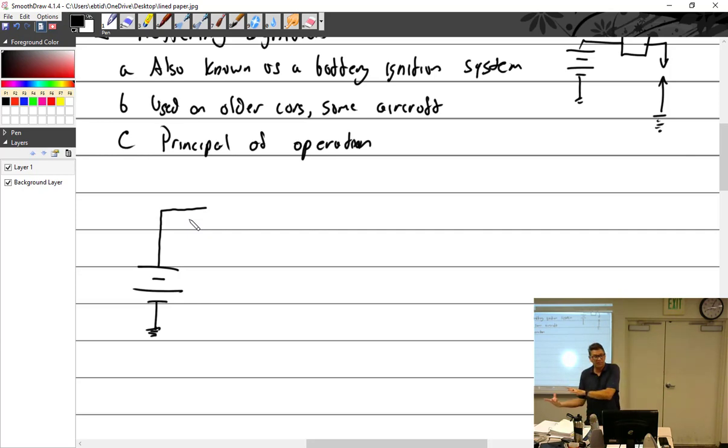One side they found out is a little richer than the other side. A rich mixture is going to burn at a different speed than a lean mixture. So they figured this out and said, okay, since we're going to use 2 spark plugs, this is how we want to do things so that it starts this great flame front and burns perfectly across, and that's the way it should run. And if you shut off either one of those spark plugs, your exhaust gas temperature instantly starts rising.